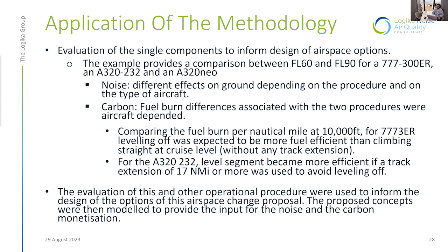So comparing the fuel burn per nautical mile at 10,000 feet, for the 777 the leveling off was expected to be more fuel efficient than climbing straight to cruise level, while the opposite was true for the other two aircraft. And this difference in operation for the A320 would give an extra 70 nautical miles that could then be used to provide, for example, a more noise efficient route.